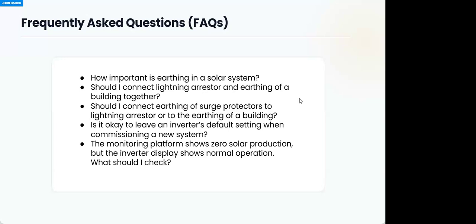So whatever external settings you are doing around that inverter to override this function, if proper communication is established between the BMS of the battery and the inverter, will not work. It will override. If you set it, by the time you go back there, you see that the charging current has changed. It is now the battery that is giving the command: oh, inverter, please give me 100 amps. That's what I need now with the way I am.